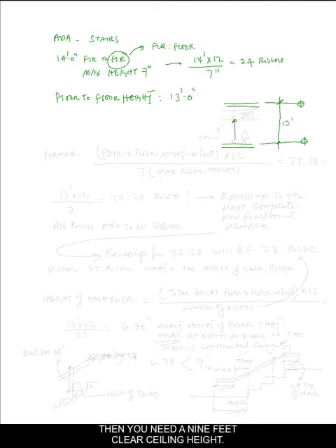Then you need a 9 feet clear ceiling height. So that is the ceiling. And then the remaining part would be for your structure, mechanical equipment, ductwork, lighting, etc. That's a very comfortable dimension to work with. So what if the floor to floor height is 13 feet?